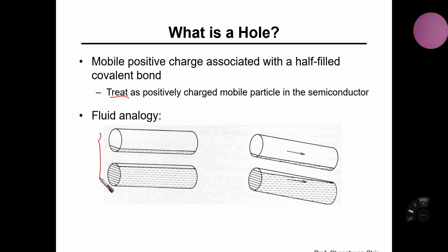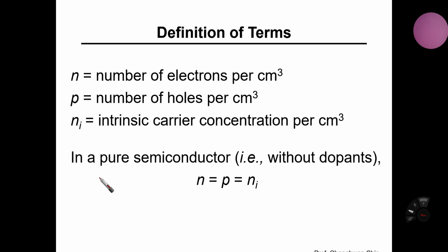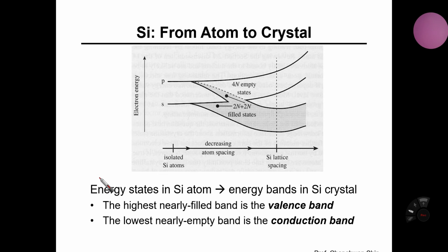And once another electron tries to fill that empty space, the hole moves to the place of the second conduction electron. So this mechanism, this process, can easily help you understand how the hole is created and how the hole is roaming around in a crystalline silicon material, diamond structures. All right, that's all. So now let's stop here and see you in the next movie clip.